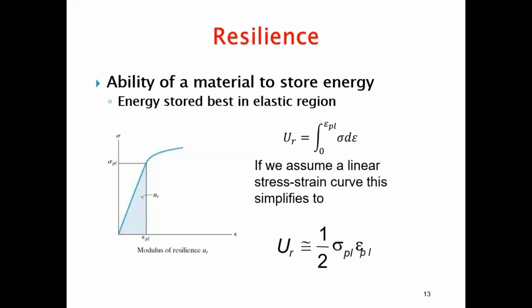Resilience. Resilience is the ability of a material to store energy, like energy stored by any material within the elastic region. It is represented by the integral of stress times d strain from 0 to the proportional limit. If we assume a linear stress strain curve, this simplifies to 1/2 times stress at proportional limit times strain at proportional limit, which equals the resilience.